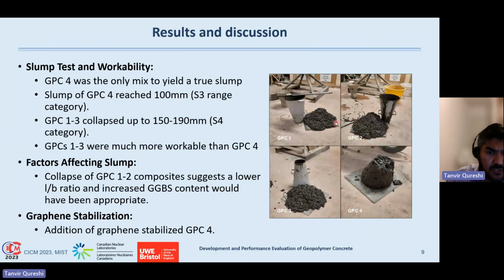And of course, this should be quite flowable because you have to know that geopolymer has a high proportion of fly ash, which was one of the initial targets anyway. And fly ash particles are spherical. They allow lots of easy flowing against each other.